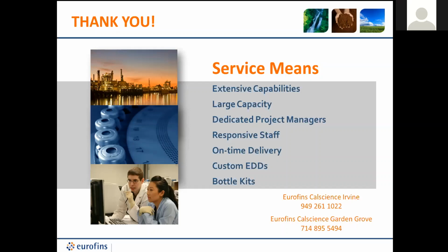And Linda, this is John Tarascus here. You're probably absolutely right that it's more a regional issue. I know we're out of the Central Valley, and the Central Valley Regional Water Quality Control Board is requiring pyrethroid testing of municipalities now. And the water quality objectives are so low that I believe there's only 3 or 4 laboratories that have been approved and have demonstrated they can actually achieve that. So it could be just a function that our local regional board is requiring that.